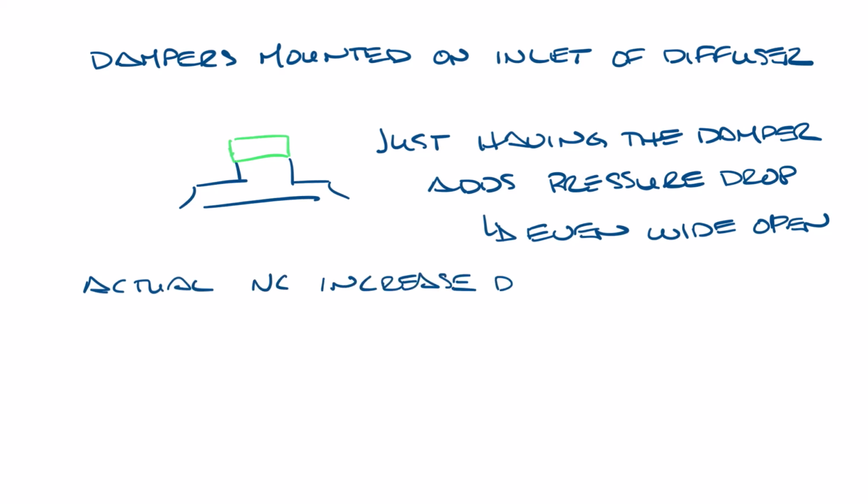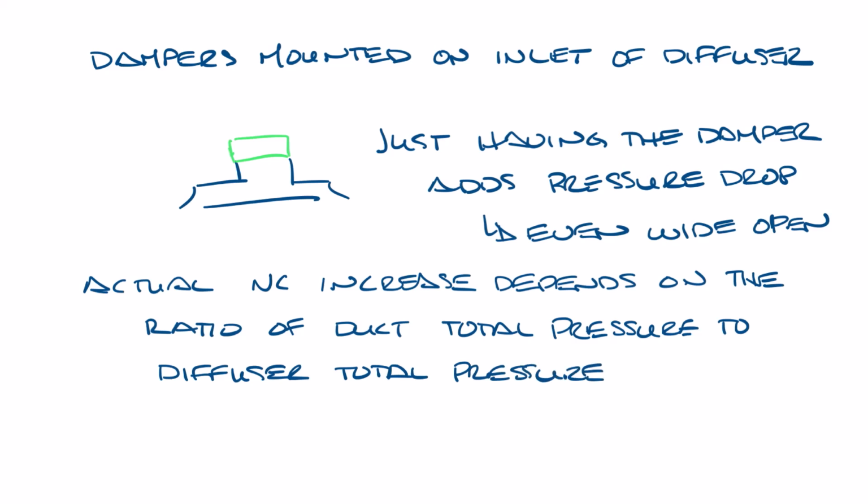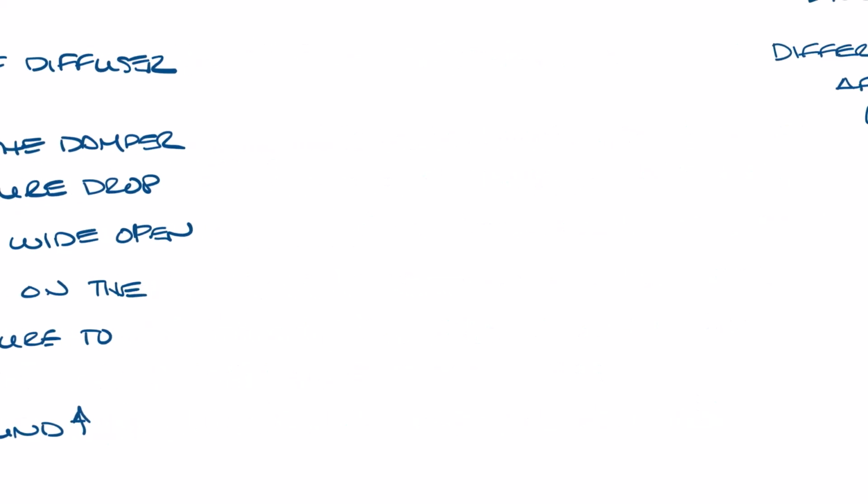The actual sound increase depends on the ratio of duct total pressure to diffuser total pressure. So as you close the damper, the total pressure goes up, and so does the sound. Let me slide this over again.